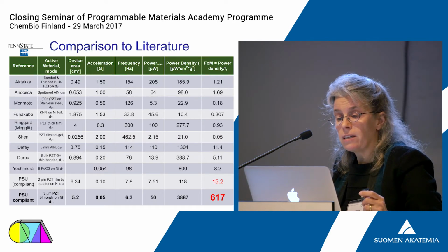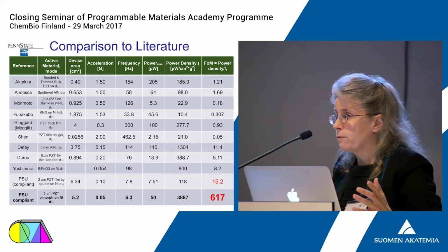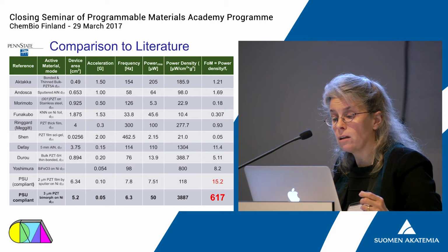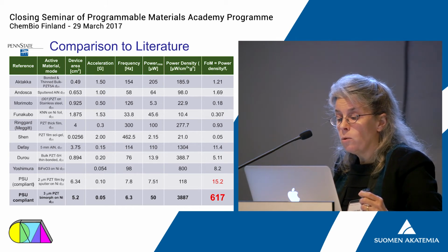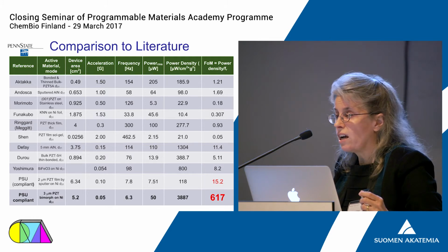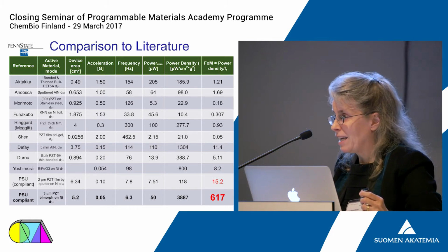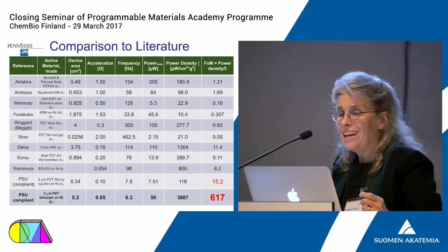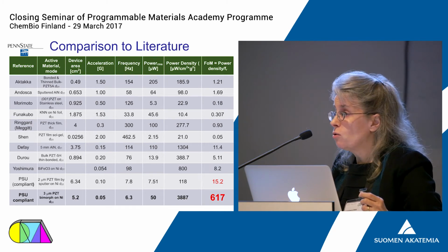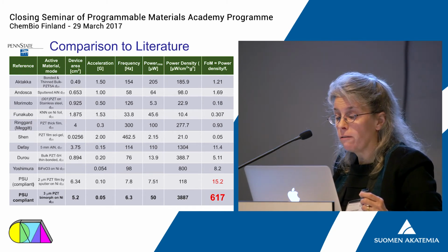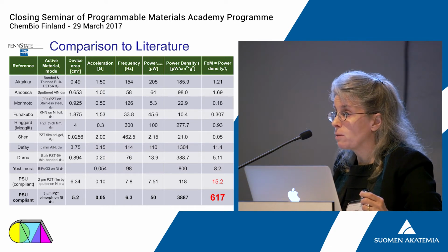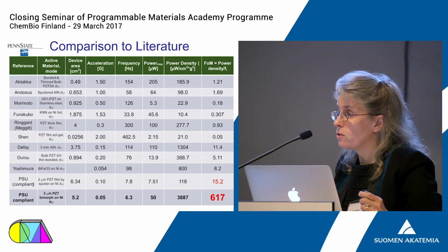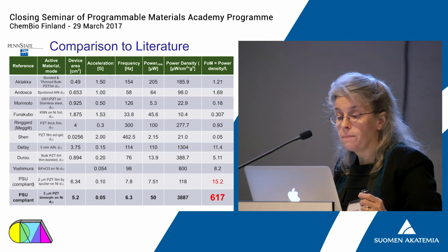So everybody makes devices with different resonance frequencies, they shake them different amounts, and so you really need to normalize all those results. I'm going to ask you to concentrate on this last column here, and you can see that when you use a material which is designed to be a very good mechanical harvester, designed to have a high figure of merit by control of the domain state, and you put it into a structure that utilizes that strain effectively, you can do about 50 times better than anything that has previously been reported. And this is large enough for most self-powered wireless sensors using ambient mechanical energy.